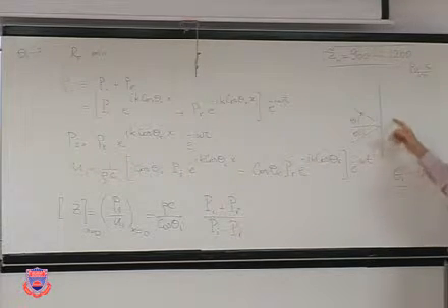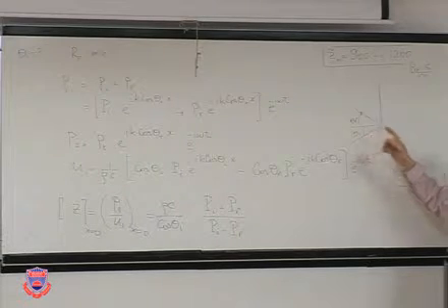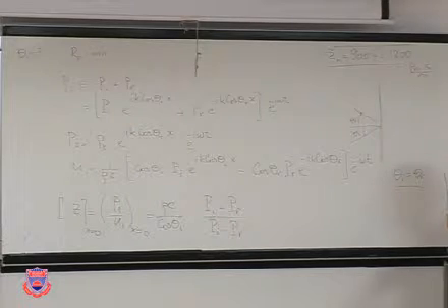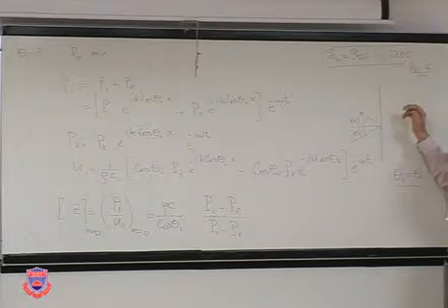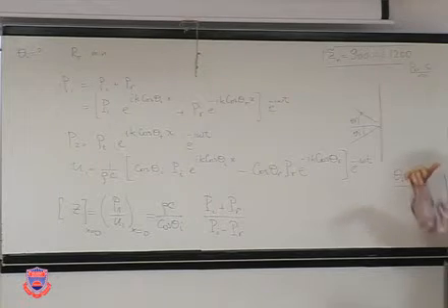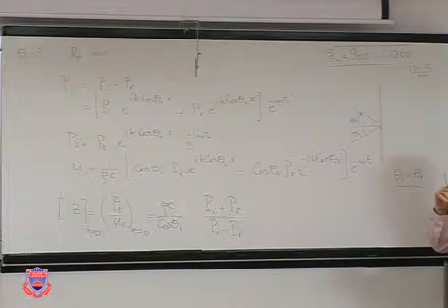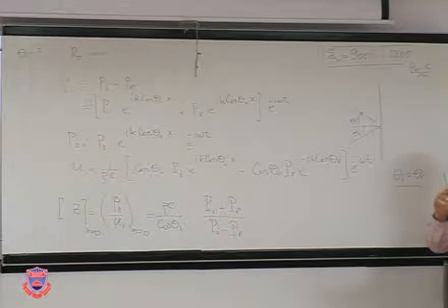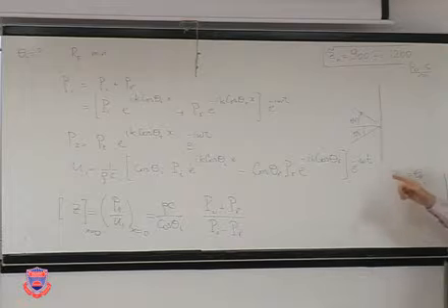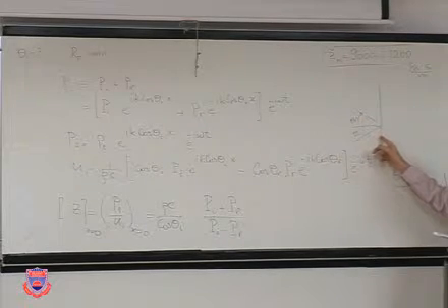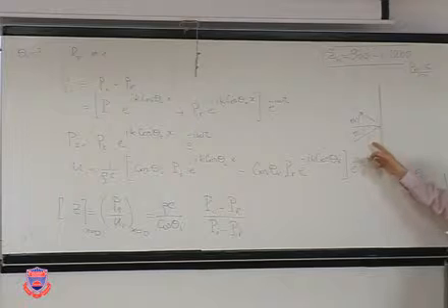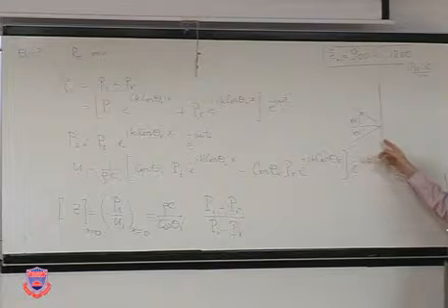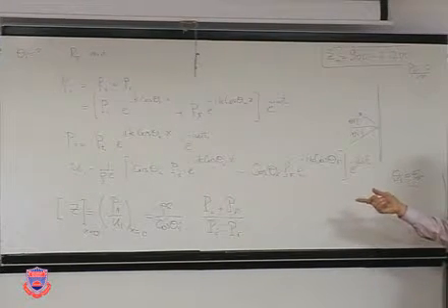Okay? And acoustic impedance, usually the types of boundary conditions we have used in the past, if you remember, we said either rigid surface, open, pressure is 0, or particle velocity is 0. But I also told you once that what happens if it is neither, something in between, then you use impedance. So here now, for continuity as a boundary condition, the normal acoustic impedance and the impedance of the surface must be equal.